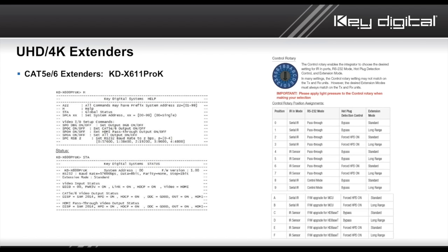Let me tell you something. I just worked with somebody yesterday who had Sony 4K displays. I think it was 4K, I'm not sure. But it was a new Sony system, or television, that had many of these things. And there was a problem. Whenever they went to their native streaming services, the web apps on the television, and then tried to toggle back to the HDMI input off of the matrix, they didn't have video sync any longer on these new Sony XPRs. They didn't have any video sync.